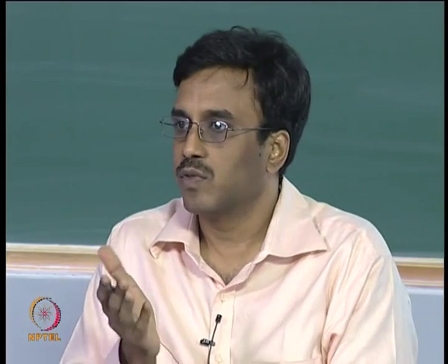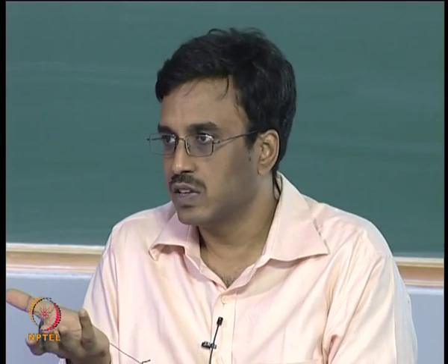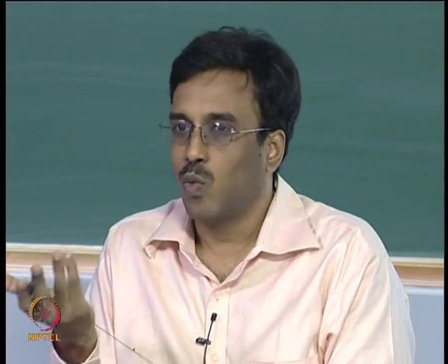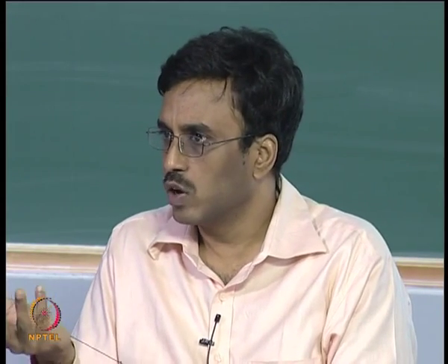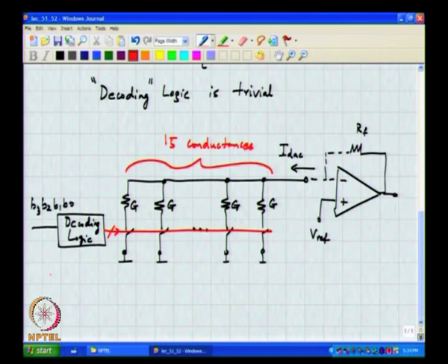So, can you name one code which satisfies that? One way of doing it is a thermometer code. So, this is the binary code as we all know, and one common thing to do is to make this a thermometer code. Understand?